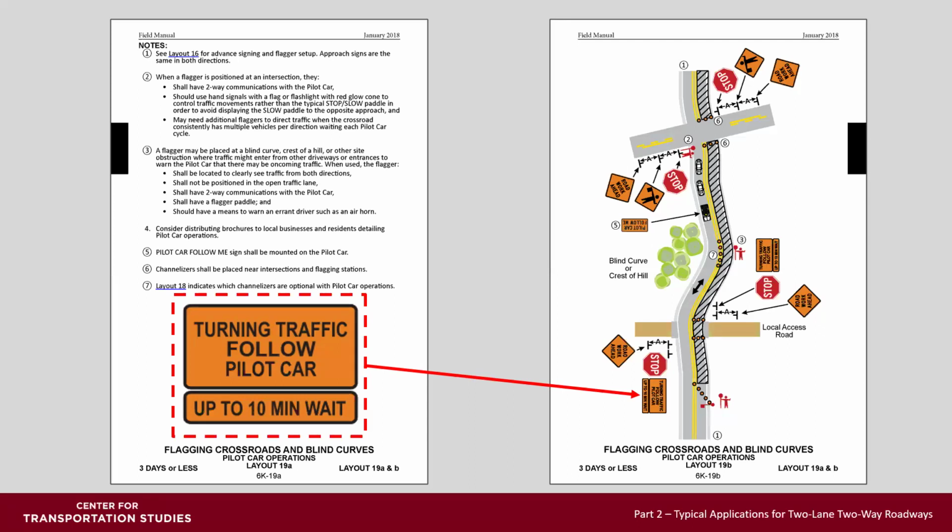Note 3 provides guidance for flaggers at locations where there are site conditions requiring some additional direction along with the pilot car. Channelizers are needed at flagger stations and near intersections. Tangent channelizers are optional with pilot car operations if the drop-off is 4 inches or less.